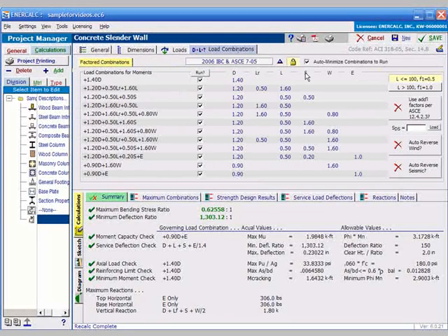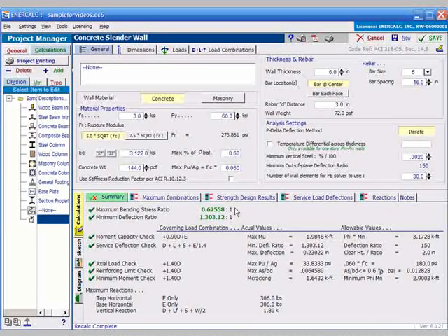Moving over to load combinations, if you've watched any other of the videos or used the software, you know this is the standard load combination screen. You can reload load combinations from the built-in database that you've defined, and you have some abilities to reverse wind loads and seismic loads. That goes through the input. Output is essentially identical for both